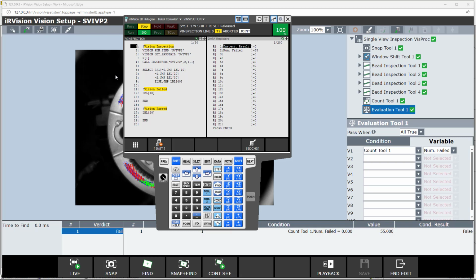On the other hand, we used the histogram. We saw on the first vision process that the result wasn't very accurate or reliable due to the lighting conditions. On the second vision process, we were able to improve the evaluation, and we narrowed down the inspection to particular points in the target area. But at the end, we needed to fine-tune the histogram values to get a better result. Also, you might have noticed that for the histogram tool, the vision process setting was more complicated and requires a lot more vision programming experience.